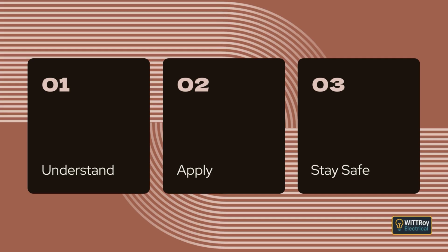Clause 3.12.6 Poles and posts. Poles and posts must be made from materials suitable for the conditions in which they will be used. They also need to be installed to the correct depth for the soil type. If the ground is very solid, such as rock, the depth may be reduced. If the ground is weak, the pole must be installed deeper or supported by other means.